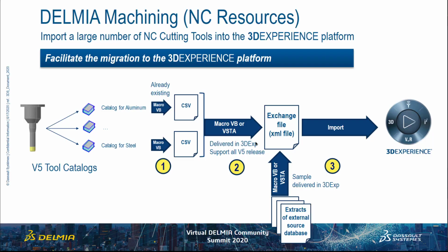The 3D Experience platform has a role called the cutting tool technologist. This role would allow you to import P21 or ISO 13399 format cutting tools that are readily available today on the vendor's website, such as Sandvik or Kennametal or ISCAR, for instance. They all have these formats available on their websites. You can download them and import them into the platform and simply use them.